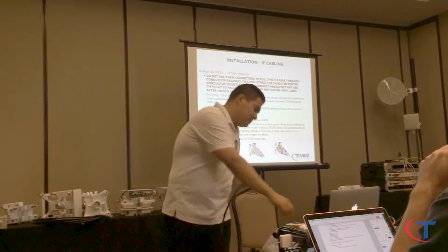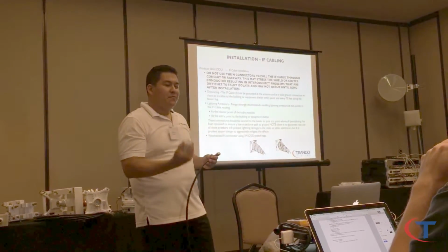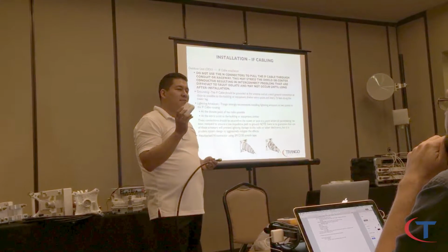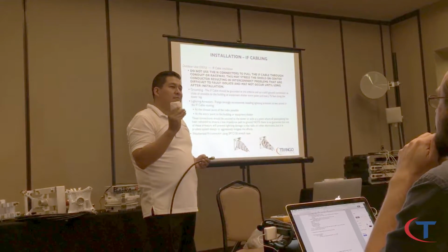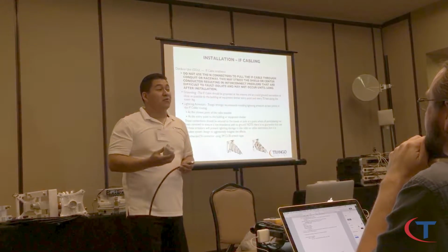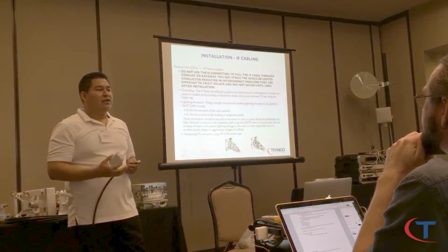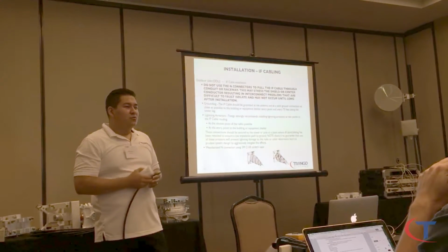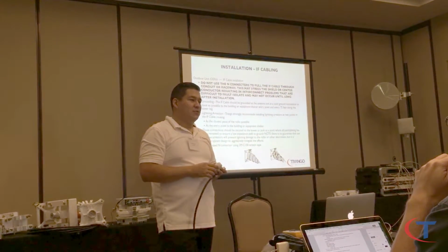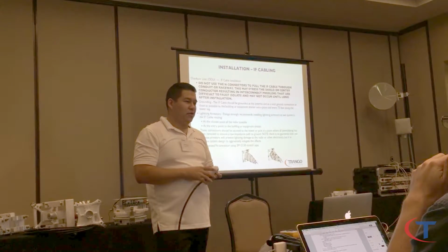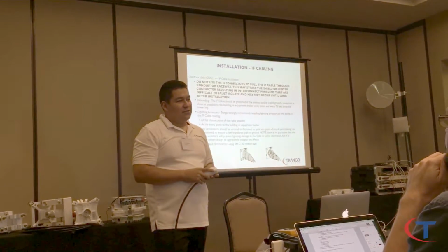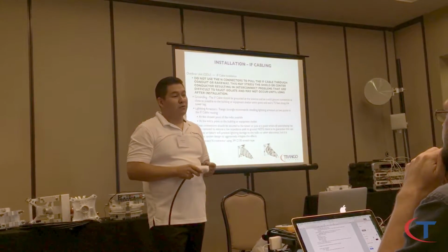Now, I want to test you guys on this one. Does this go clockwise or counterclockwise? Whichever way will promote shedding of water. Yes. But remember, there's heat involved here. When there's heat, it shrinks and expands. So counterclockwise will actually tighten when you do the installation, after the weather goes up and down in temperature. Typically you want to put it counterclockwise.